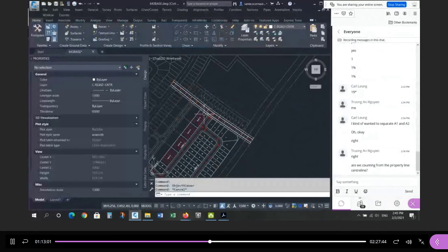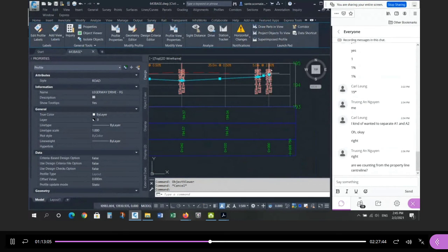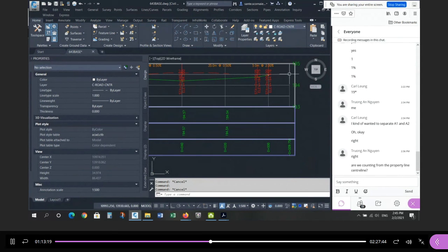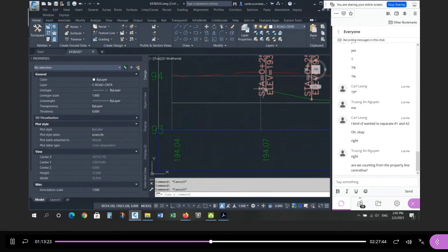Why? Well, if you look at the design of the profile, the range of the profile is inside the range of the horizontal alignment. The horizontal alignment goes all the way to here in the plan view, but the design for the road starts here. So for this half of the road, the plan exists, but not the profile. Same thing at the other end. The design ends here, but there's more horizontal alignment to here. So the range of the corridor model for the default build is the horizontal limits, not the vertical limits. And when there's missing vertical, it assumes it's 0.